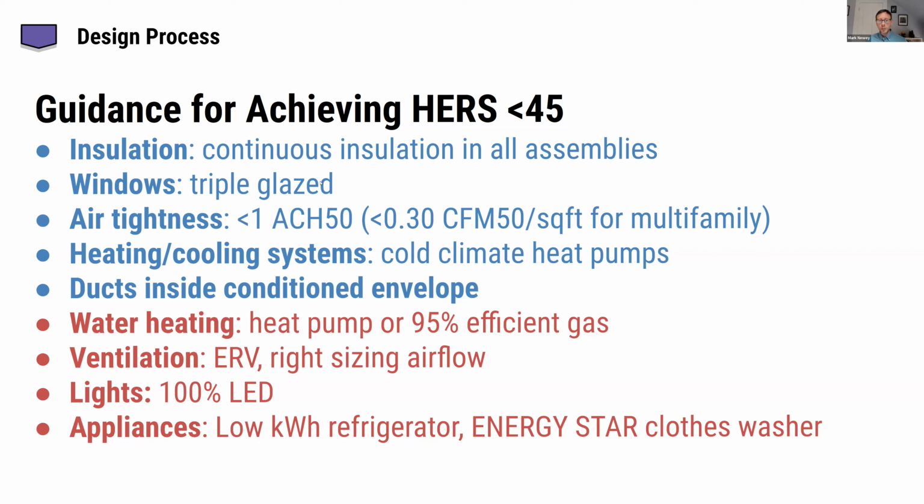Ventilation under the new stretch code, every home and every apartment or condo should have an ERV that will help with these HERS indexes, and depending on the code you're under, it may be a mandatory requirement to begin with. And getting the airflow right. There's too little airflow, which is not enough to meet air quality needs, and there's too much airflow, where you're creating an energy loss without needing that much airflow for air quality.